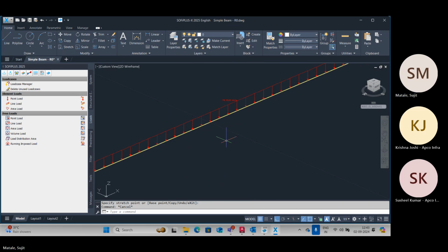Right. But if you ask me whether to use this one or that, it is not like that. It is as per the right usage, depending on what you need at that time. We will see it. I have a crash barrier load right on top of my slab, but not on any beam. It's on my area element, not at the edge of the area element. It has a 250 mm offset, and an AutoCAD line curve moves there, so I will select that line and my free line load will be applied on it.